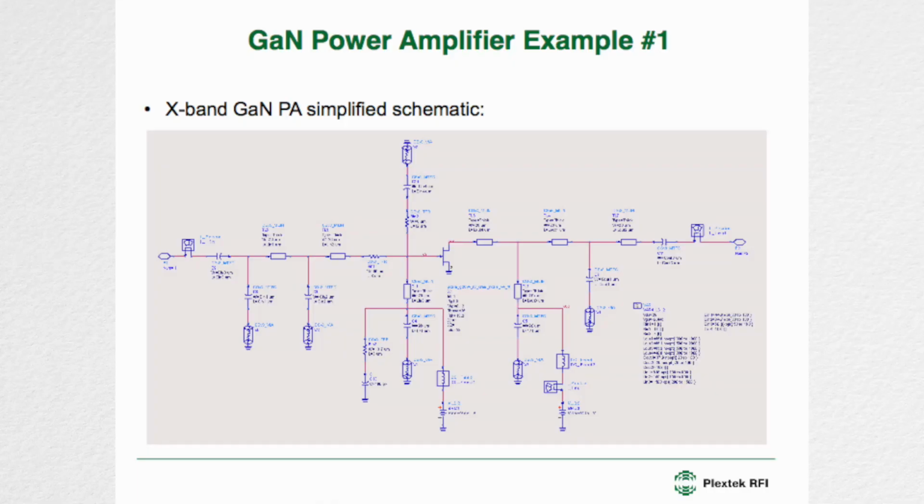Now, we can then go on and look at the harmonics and look at optimizing the impedances at the harmonics. And in honesty, we seldom go beyond the 3rd harmonic when we're considering this. And how much use this is is entirely dependent on how accurate the model is. This is a schematic. We just put this example together for illustrative purposes for this talk, so we never went beyond the schematic stage.